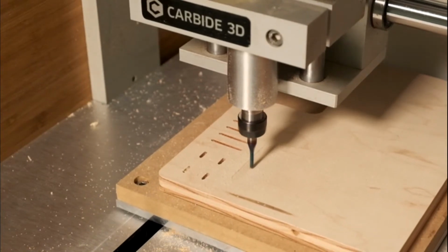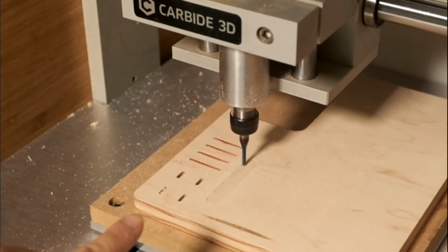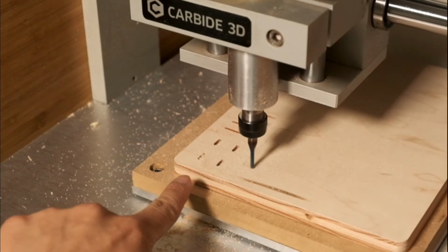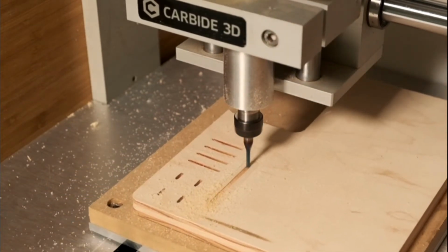All right, I'm back. This can definitely go faster. Or actually, this is the first step down. So this is going to be easier because I programmed this in as 1/2 inch. So it's cutting what it thinks is the first step down. That's more like it. We can still go faster though.